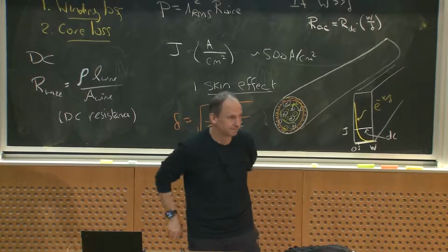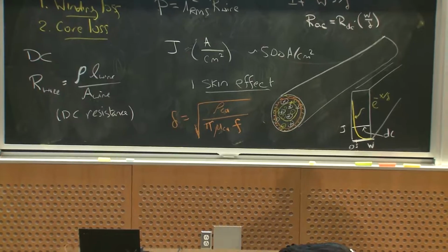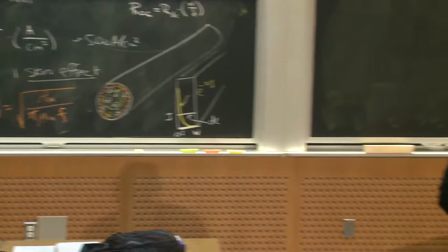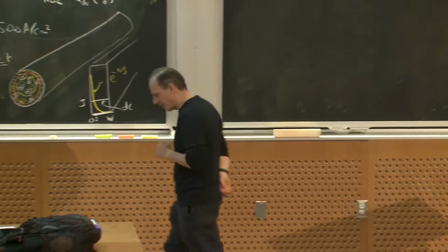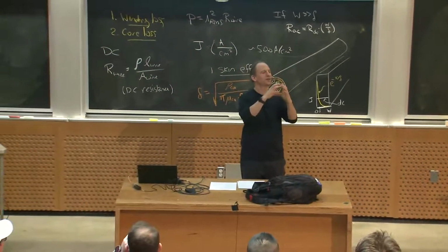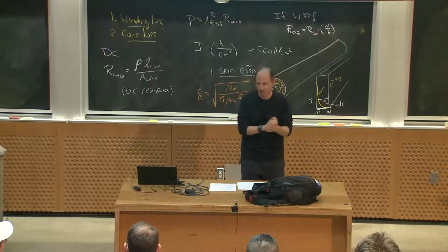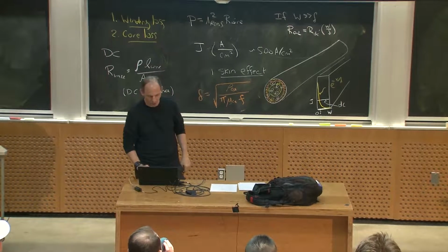Would you like to do this instead of having one big conductor, like many parallel conductors? Yes and no. Yes, you can, but you just can't have parallel conductors because, indeed, what is one big conductor except a bunch of parallel conductors? But what you can use is something called Litz wire.